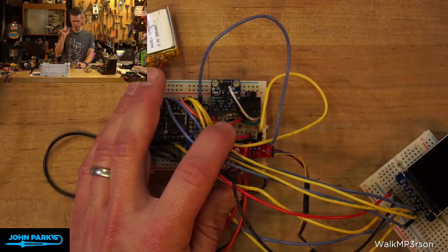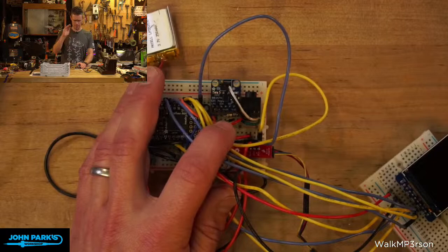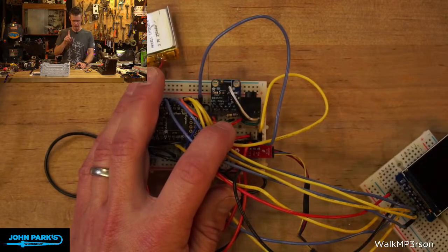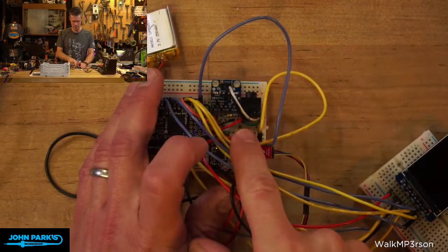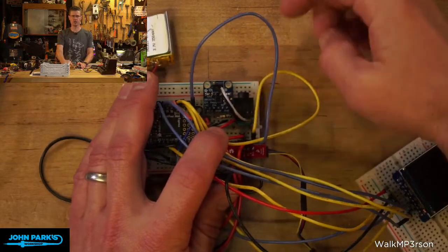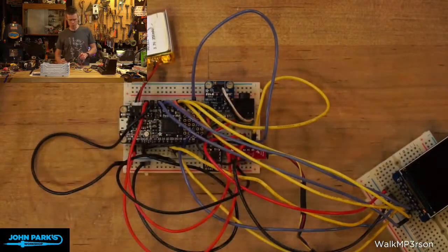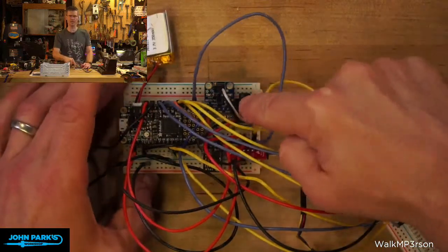You can then use different combinations of resistors or wires shorted to the voltage input, and that will change the setting. It's just sort of a startup thing. You can't really do this actively, and it's just a few increments. You can't use a potentiometer with it. But I've put a 100K ohm resistor from gain to the voltage in on that, and that just drops it down to 3 dB, which makes this work pretty well for headphones and line out.